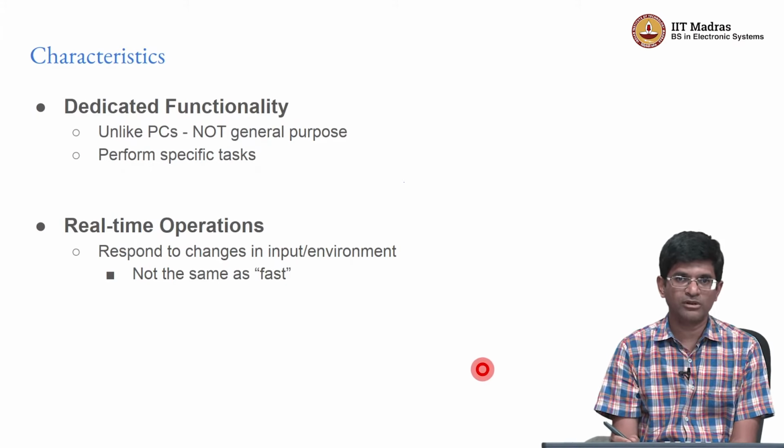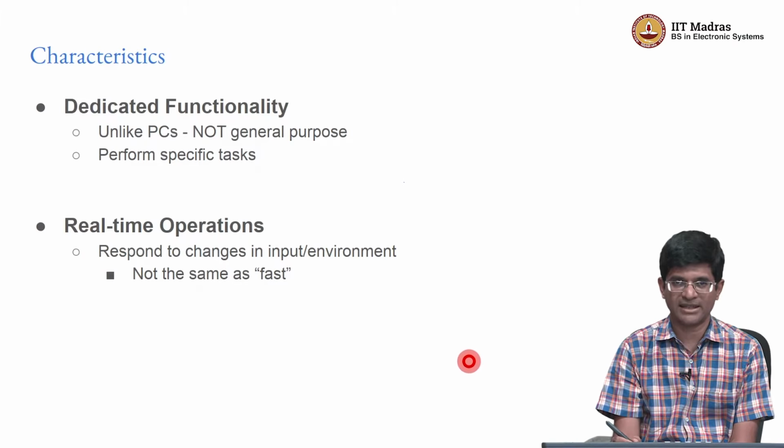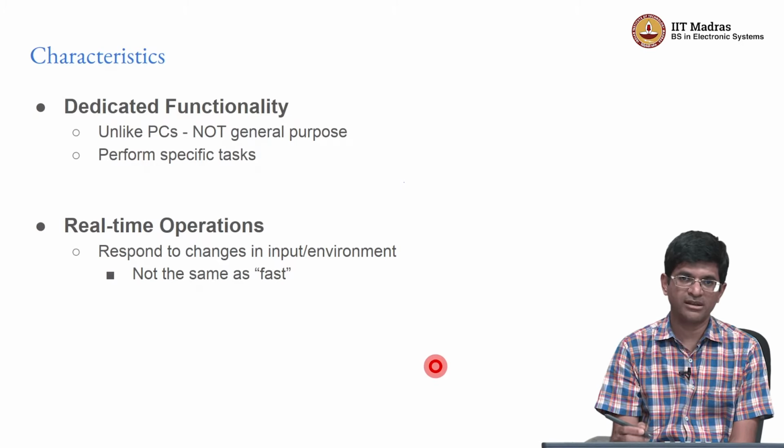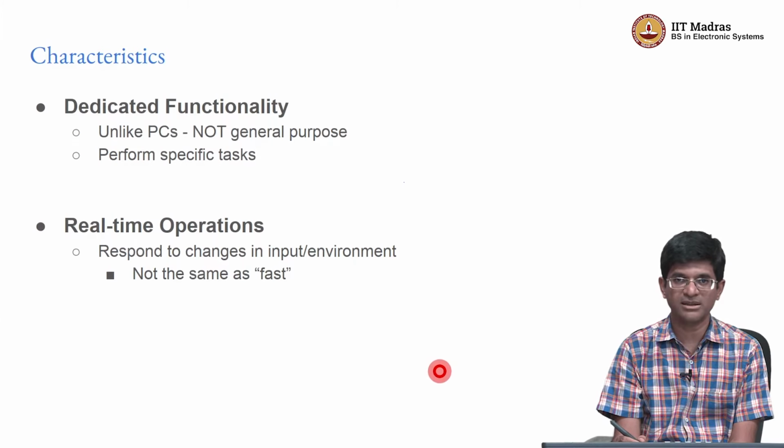So, very often what you will find is that real time constraints in embedded systems are talking about time durations on the order of milliseconds. That is, you need to respond to some kind of a stimulus within a few milliseconds or so. And in the context of a computer, a millisecond is a very, very long time, because after all, when you are working at a speed of more than 1 gigahertz, it means that a single clock cycle inside a computer is only 1 nanosecond long, which means that 1 millisecond is actually a million such clock cycles.